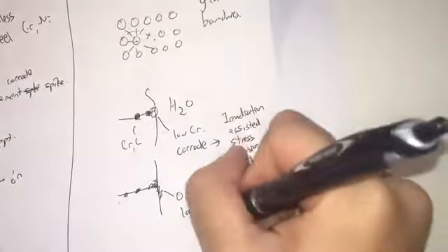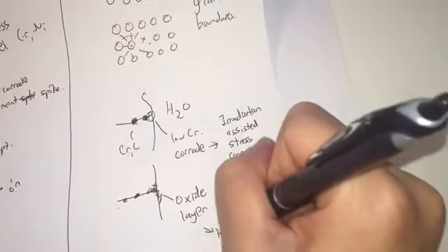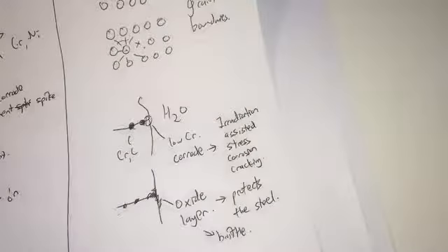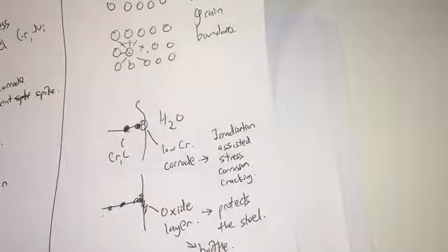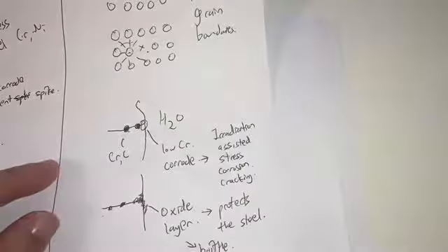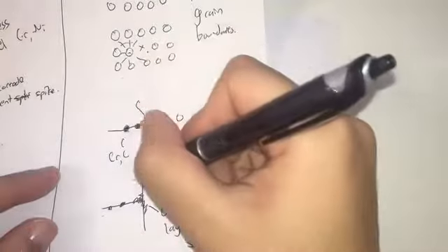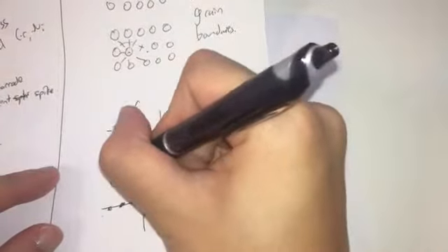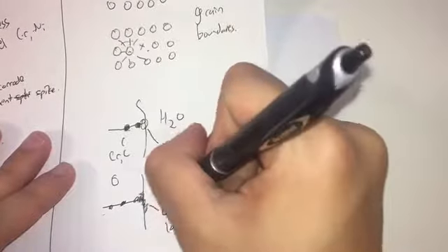But the thing is, this is also brittle. This is an oxide film that is brittle. Well, does this oxide film always stay here? Again, not necessarily, because when this reactor pressure vessel is subject to some external stress, creep can occur.